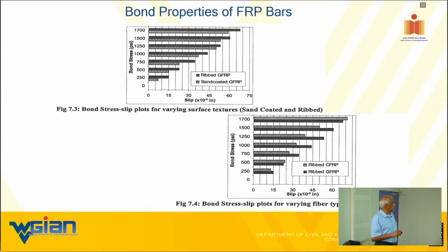I want to highlight one more item: make a comparison of this with steel. Steel, for the same bar diameter, same concrete strength, same cover distance, is slightly lower by about 10% or so. For our design purposes, we don't even say it is lower, right? It's in the ballpark range. That's how we will say it and leave it. See what I mean?